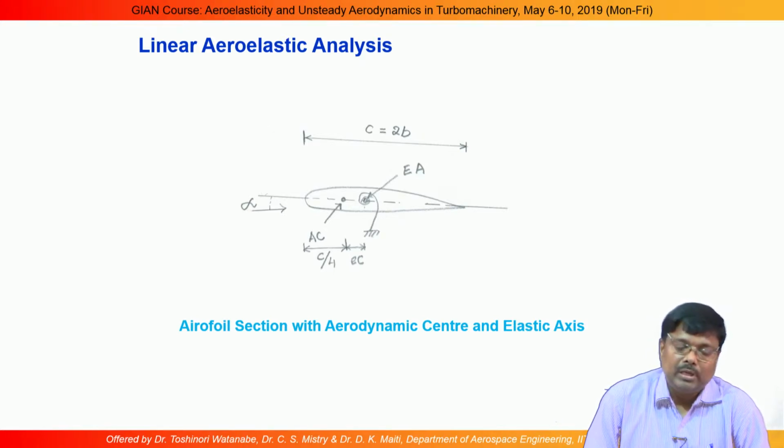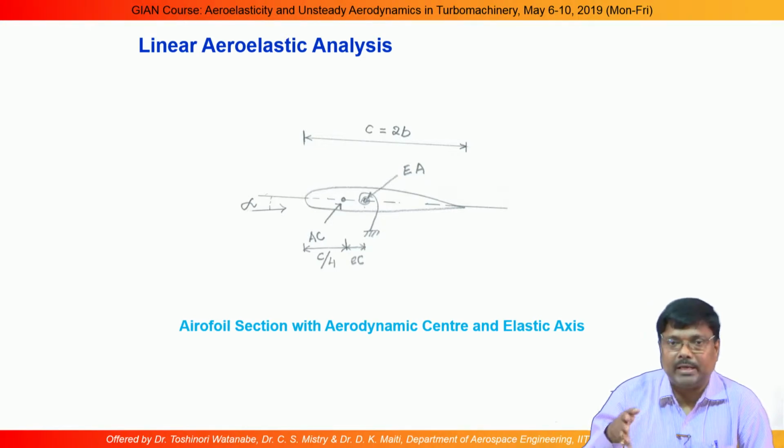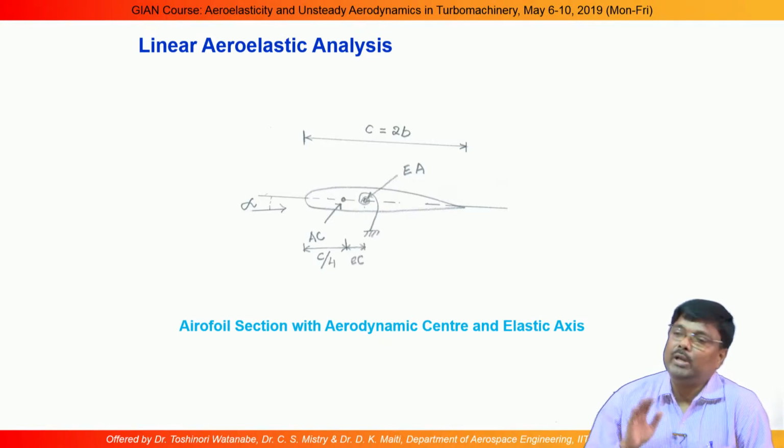For a different configuration, depending on the position and orientation of the wing, bending may come. That is why usually we use the torsional equation, which is free from bending response, that is, uncoupled from the bending. So, we consider an aerofoil section with only a single degree of freedom, which means rotation about the y axis, the pitch angle. When the aircraft is flying, there will be an angle of attack.